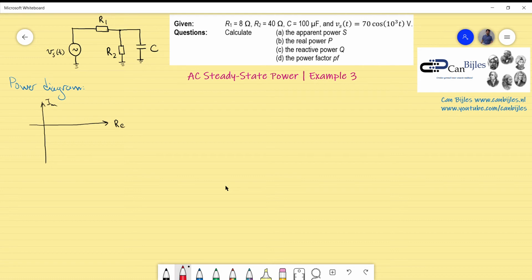So if I have the real power here, that's P, and I will give in green the Q, it will be minus jQ, and the vectorial sum of that will be the apparent power. This is a very important sketch, and we also have the phase between the apparent power and the real power, and we know that S is equal to P minus jQ.